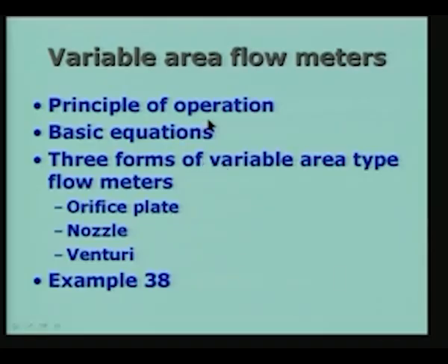We deliberately introduce a change in the area. Because of the change in the area, the velocity of the fluid is going to undergo a change. Because of the change in the velocity, there will be a change in the static pressure, and we measure the static pressure and relate it to the flow rate which is being measured. Of course, we will have two different cases, one incompressible corresponding to either liquids or gases flowing at very low velocities, and if the velocities are not very small or moderately high, then some compressibility effects may be important in the case of gas flows.